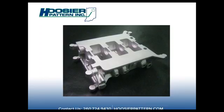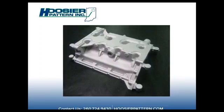And if you have a customer that comes to you to have a casting made and their draft is rather wonky, or it's in the wrong direction or attitude for you to mold it in your shop, this is an option. With no set parting line, you can figure out the best way to get the metal into the mold. And you can simulate your production molding in this. You can simulate either horizontal, vertical molding, floor molding, manual molding. We can simulate anything you want to do to figure out how to make it work before you go to production. That's just for prototypes.